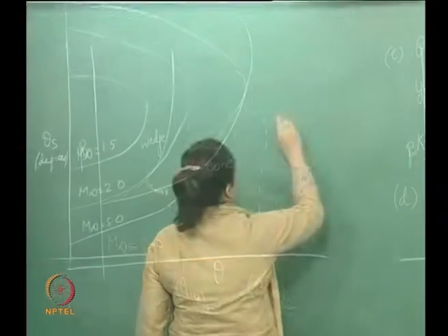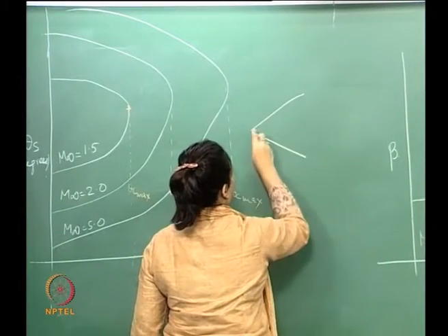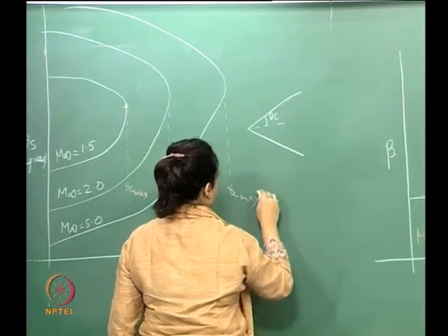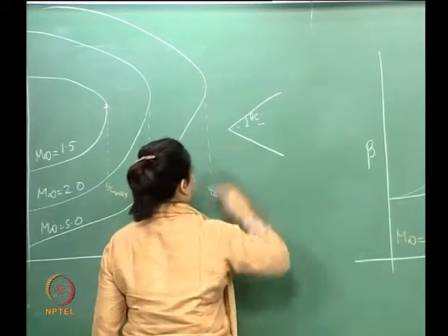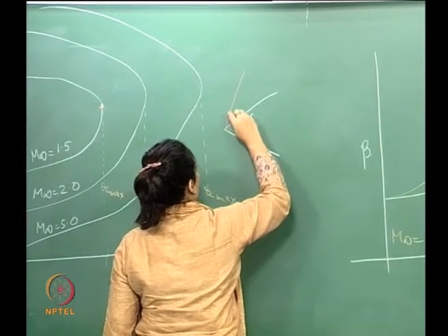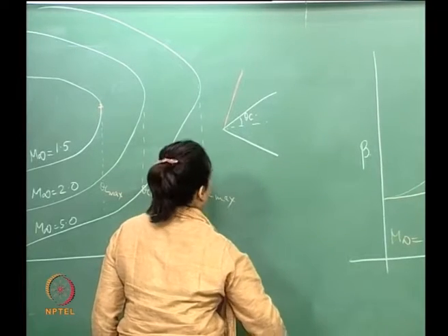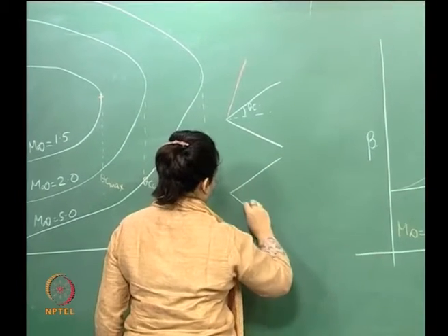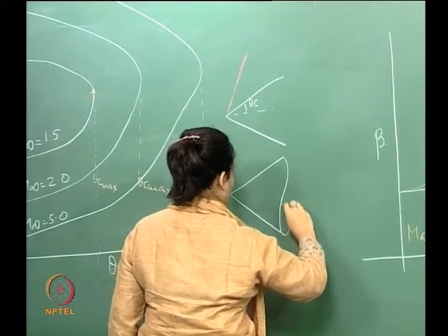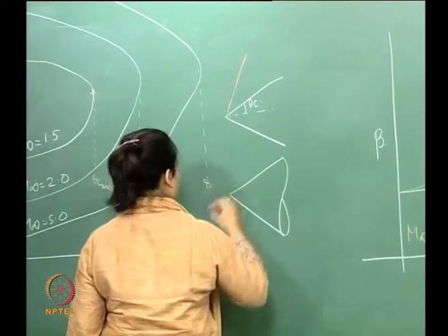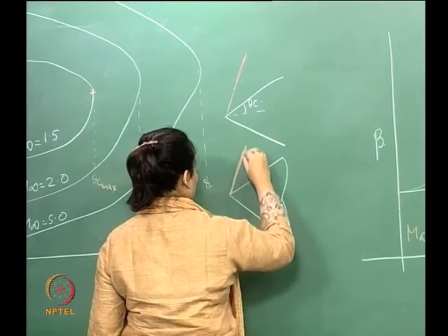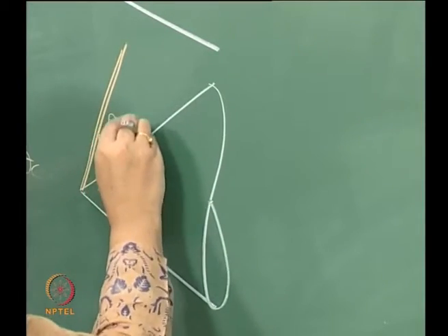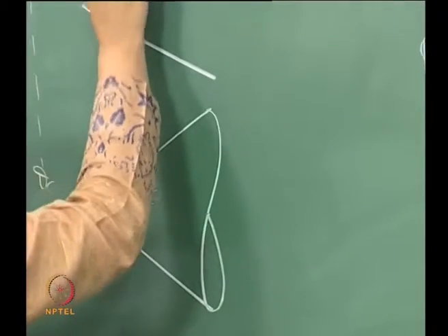So, essentially, if I were to just plot this out, this was our 2D wedge, and so then we have a shock here, and I am drawing the same thing over here for the cone, and again I have a shock wave, and again this is theta c, this is theta s, this is your beta.